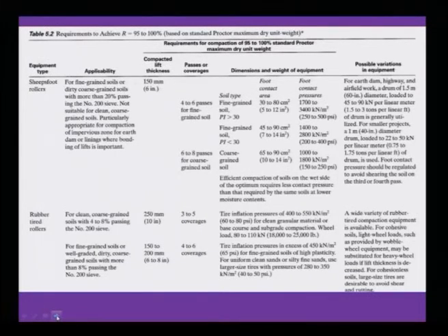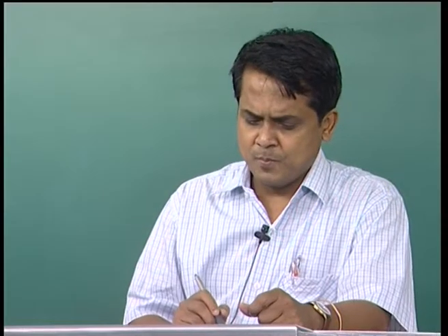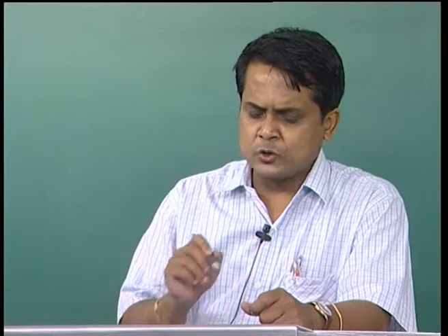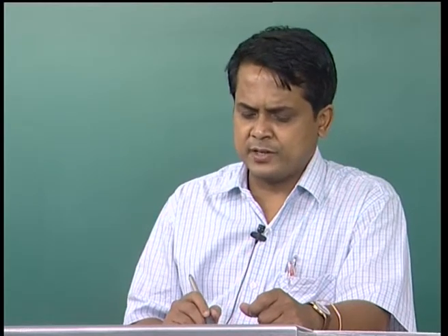Sheepsfoot rollers are applicable basically for fine grained soils. As I said, clay is a fine grained soil, or dirty coarse grained soil with more than 20% passing the 200 sieve. It is suitable for fine grained soil. Then for which soil is it not suitable? It is not suitable for clean coarse grained soils.